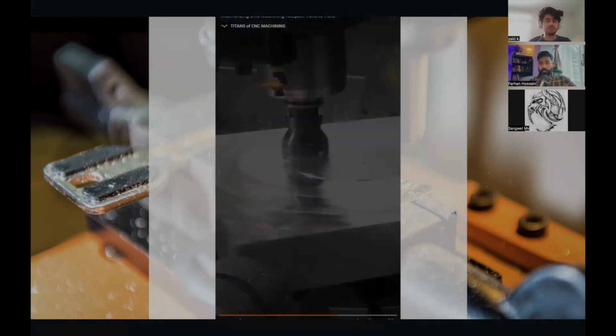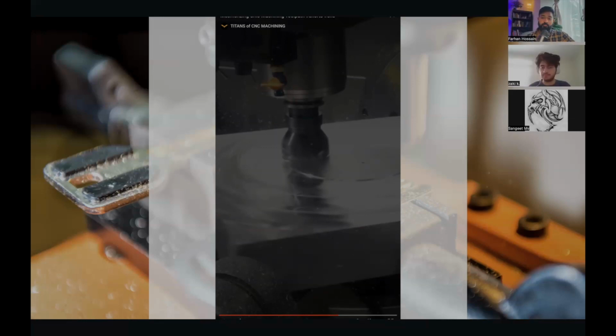Yeah. Does this cutter work for every metal or just for a certain type of metal because of the strength? Yeah, a very, very good question. There are different unique cutters for different materials for different things. For example, you can imagine cutting plastic is very easy, or wood is very easy, or in other words, they're soft. So remember the material property of hardness. The harder the material, the more difficult it is to cut it, because the cutter tool has to be harder than the material. So that's one of the rules to think about.